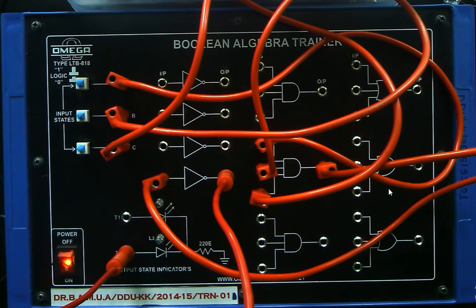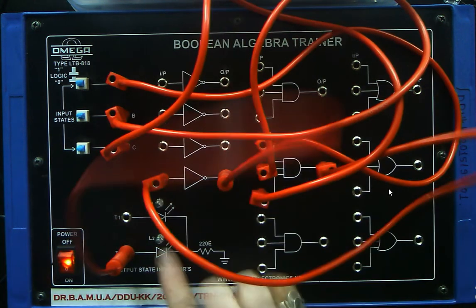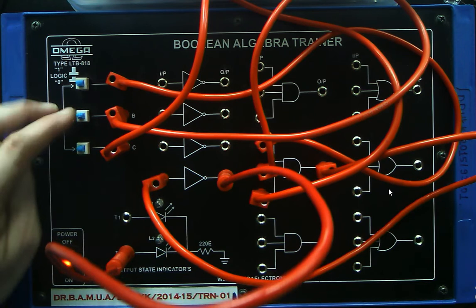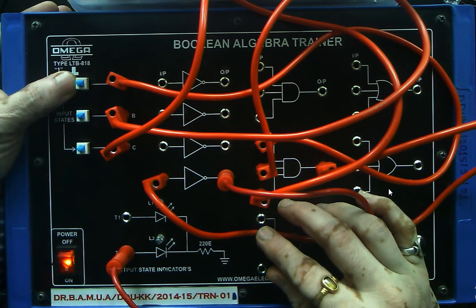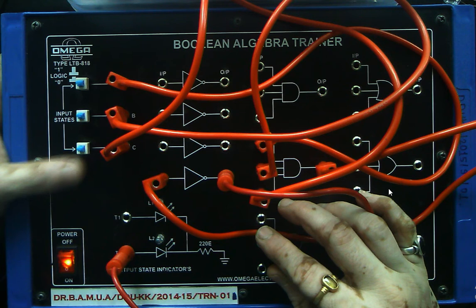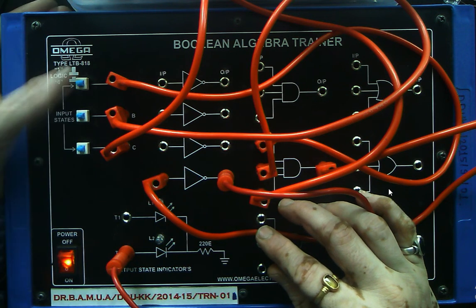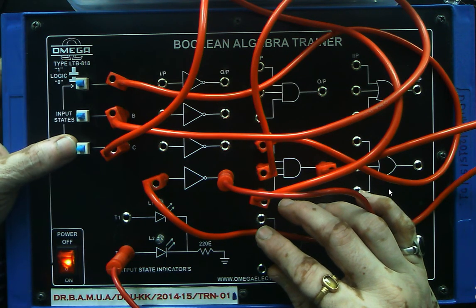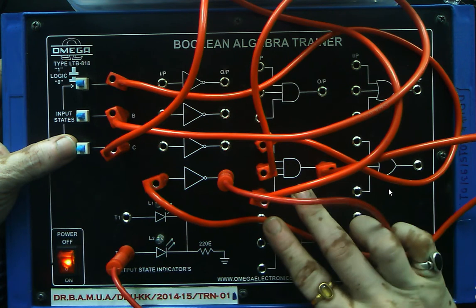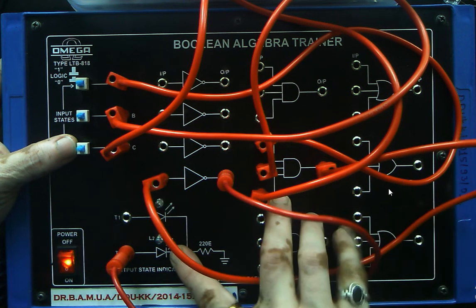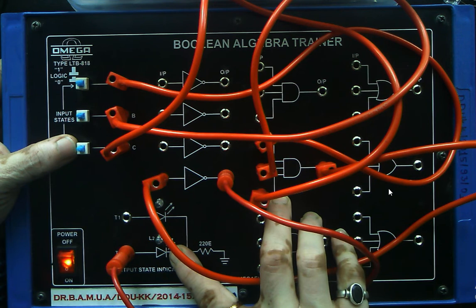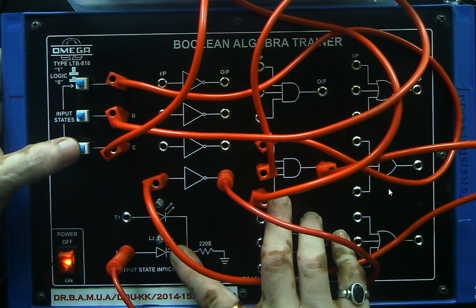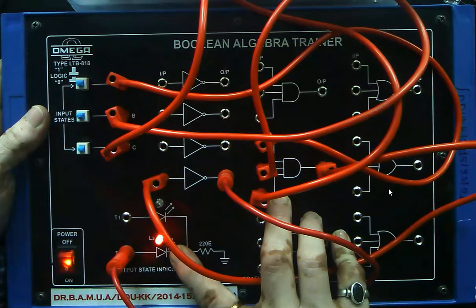Okay, now you have to focus on this LED and the status of these three switches. So at this condition, you can see all of the switches are in high status. If it had been simply the output of the AND gate, the output should have been high. But here in this case, you can find it is low. Now, if I make any of the switches low, you can see you have a high output.